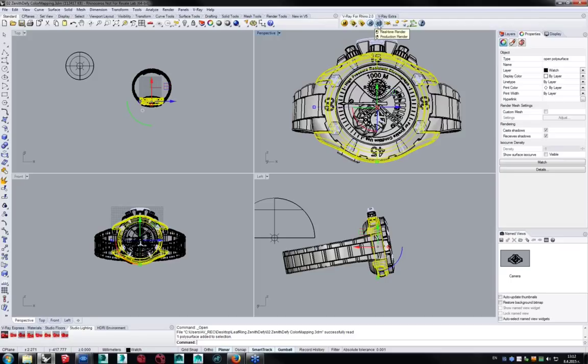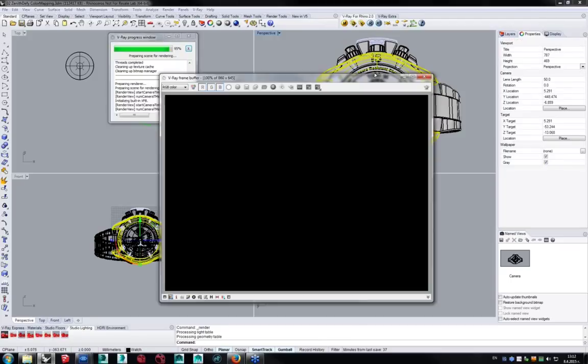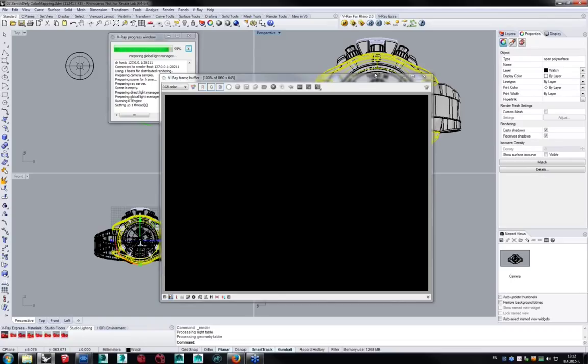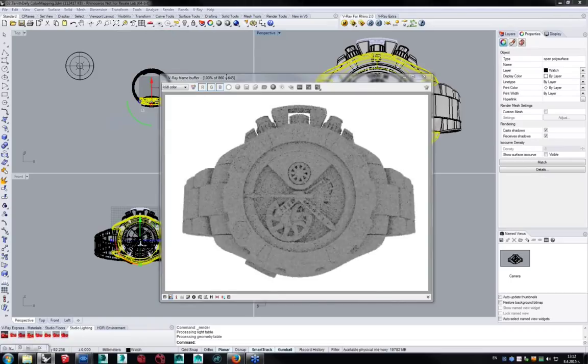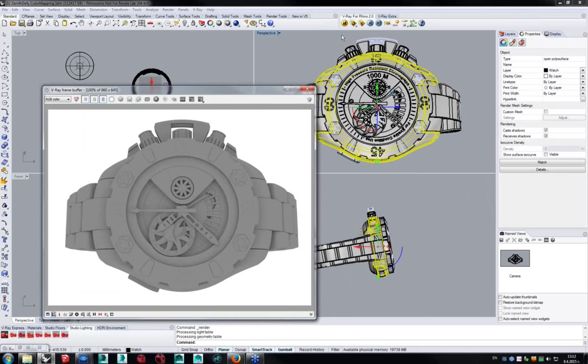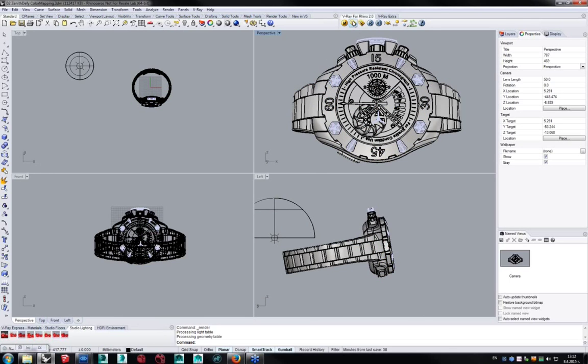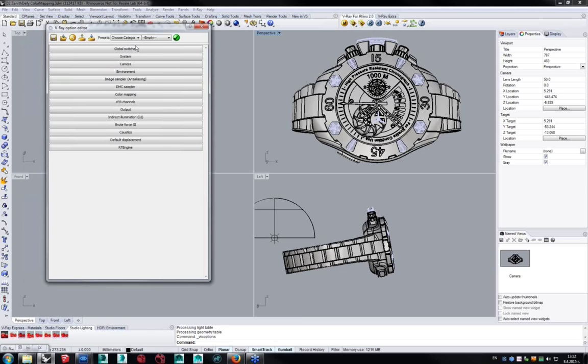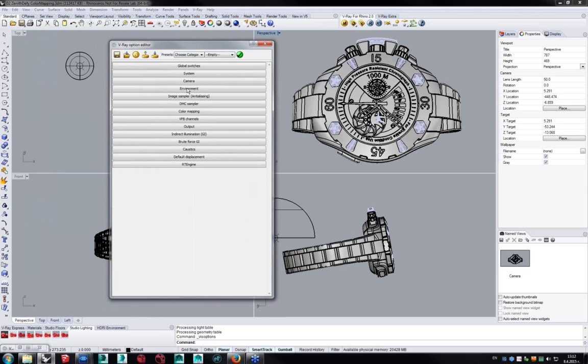Let's say you have built the model, you have done some testing with the dome light that I just showed you in the real-time rendering, and you're kind of happy with what's going on, but you need to continue and create custom shaders, custom lights to be placed, and you want to make sure that everything is correct. So this is the V-Ray RT again, but since we want to go through the whole process of rendering, I will be using actually the production renderer. So just stop that, and I will just cover a few topics of the sampling and the color mapping.